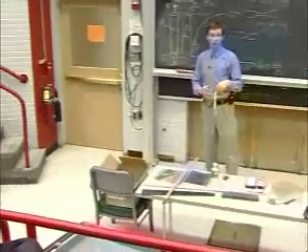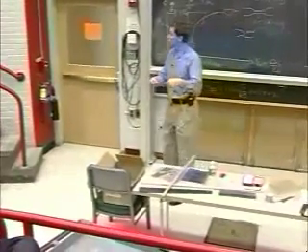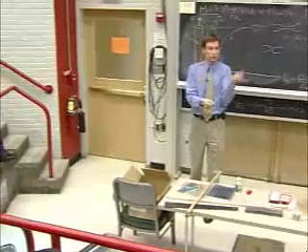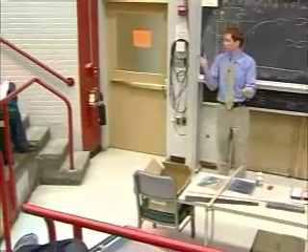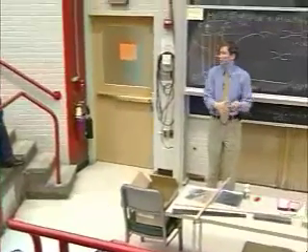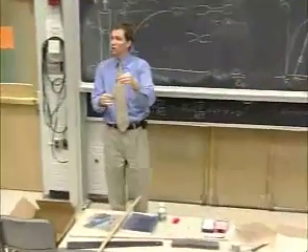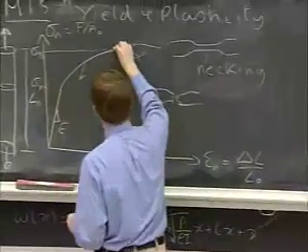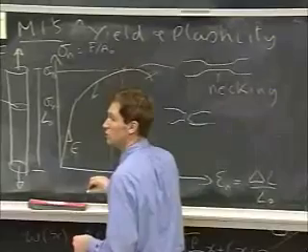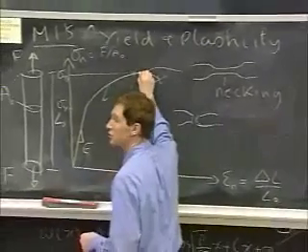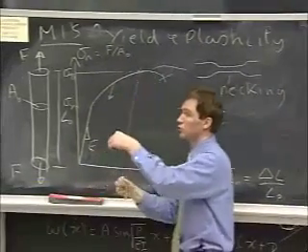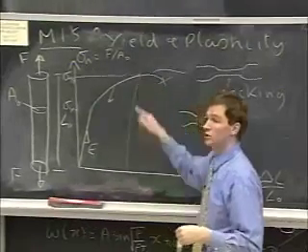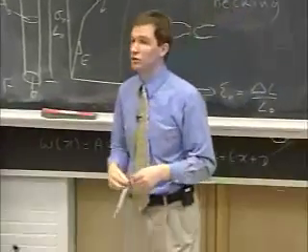You just basically roll it into sheets, but the deformation you're doing is plastic deformation, because you don't want it to spring back elastically. You want to permanently reduce its thickness. So this has seen a lot of plastic deformation. In fact, you more or less reduce it all the way up to this point, which also explains why there isn't much additional deformation. When I pulled on this foil, it broke in a pretty brittle manner without much additional plastic deformation occurring.